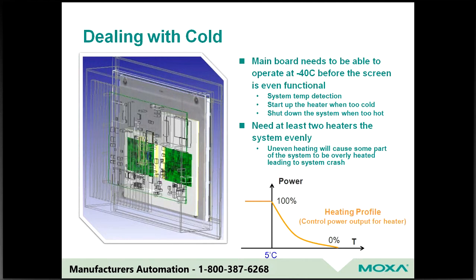You also need to have an internal mechanism that can sense temperature, and the reason is that we want to have a heating profile, an intelligent heating profile. So when we reach a certain low temperature, that heater turns on, addresses directly the LCD screen, not necessarily the internal unit, and once it reaches a certain temperature, it can shut off. And so you see this graph here at the bottom. It's adaptive, it's dynamic. It's not just turning on the heater and then turning off.